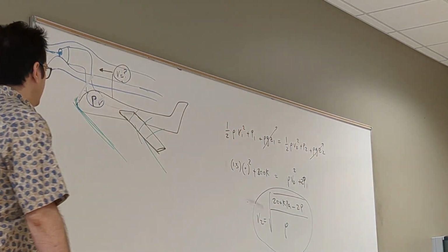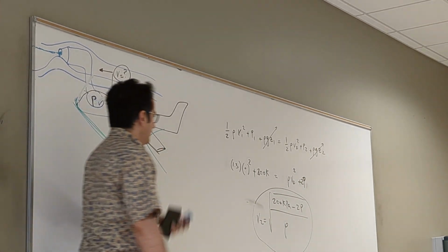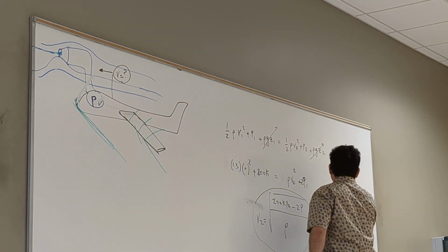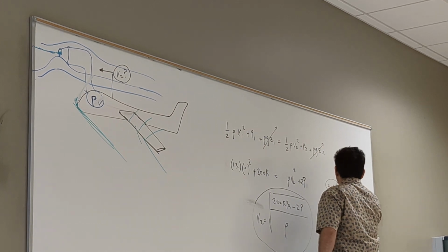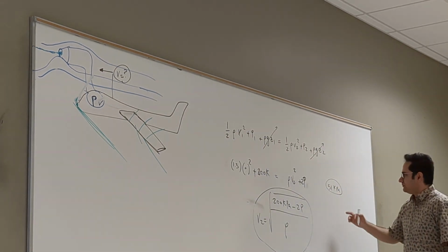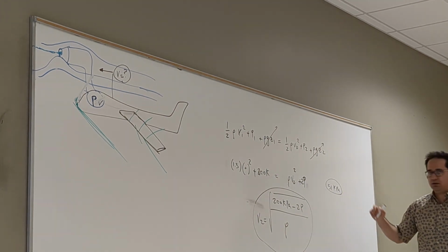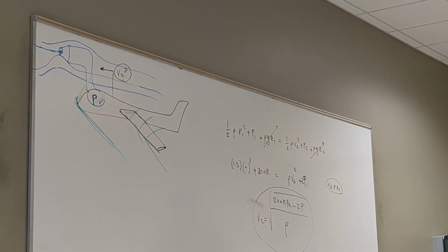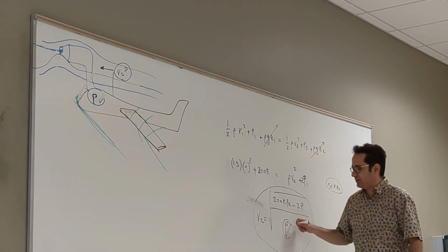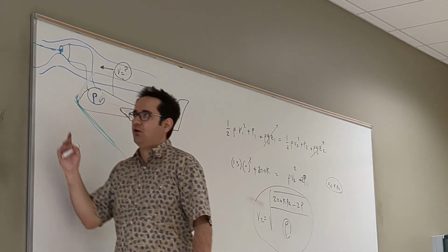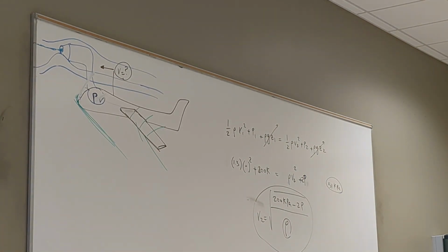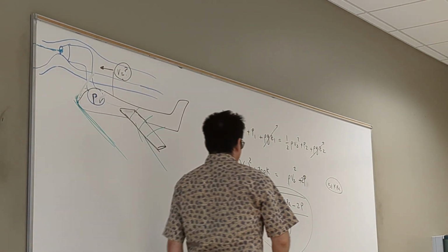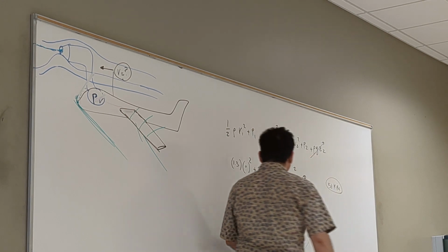So let's say the sensor here measures the pressure as 51 kPa at a particular time. So put 51 kPa: 2 times 51 is 102 kilopascal, minus 200 kilopascal gives 98 kilopascal, divided by rho. Because we assumed incompressible, the density is constant all over the streamline, so you can use the density here, 1.3. You put it there and you get V2.